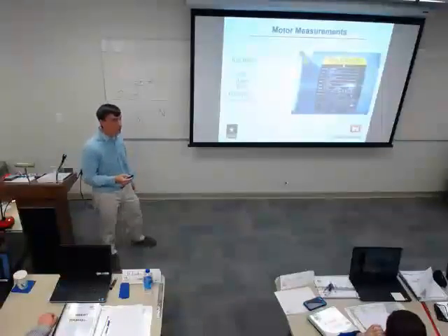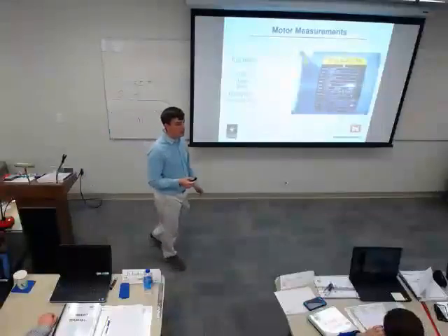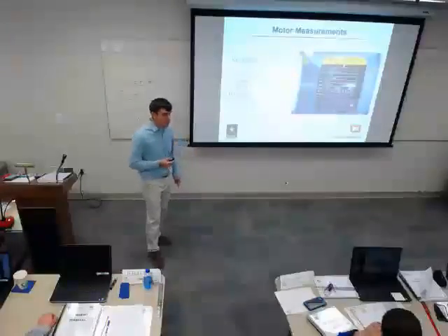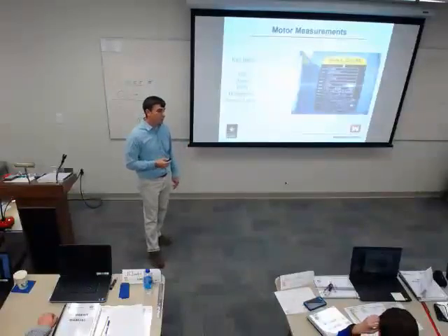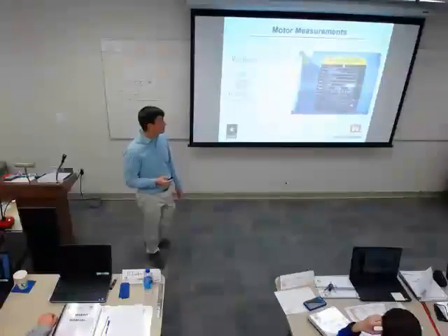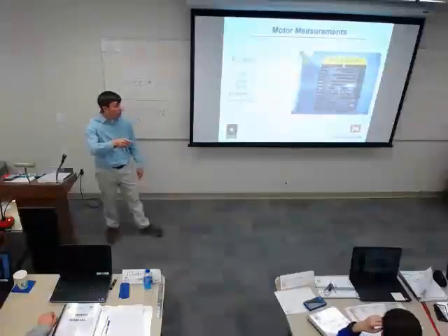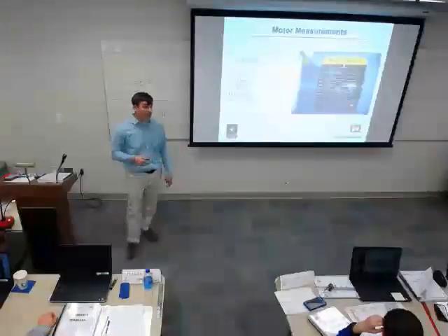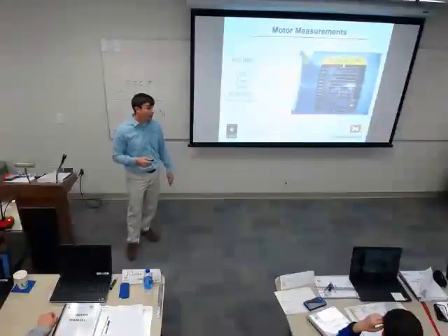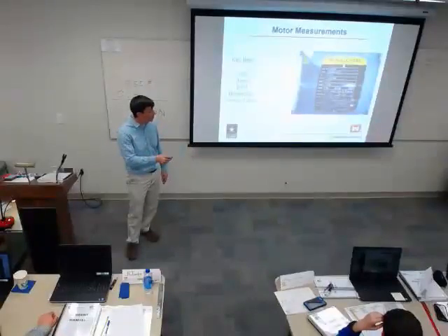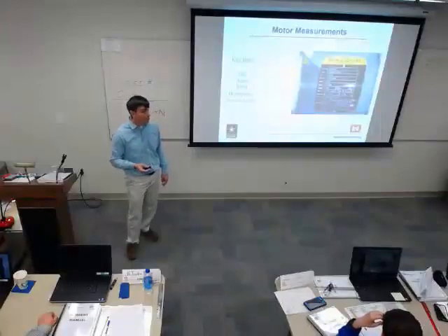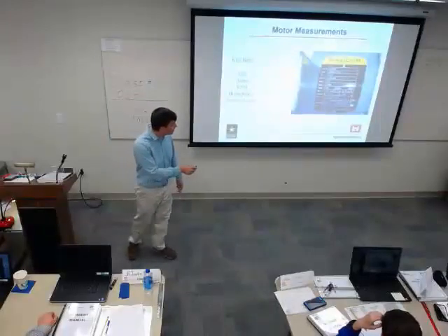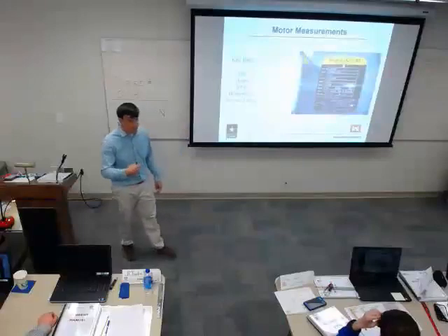And with that, it doesn't blow up the motor on initial start, because when it initially starts, it needs more power. Correct, it's only at startup. Even your startup current is going to be higher than that 25%, but it's built to withstand that. But this motor is definitely not built to withstand running at 3 amps forever at 230. It'd be too much, or even whatever 2 times 1.25 is.